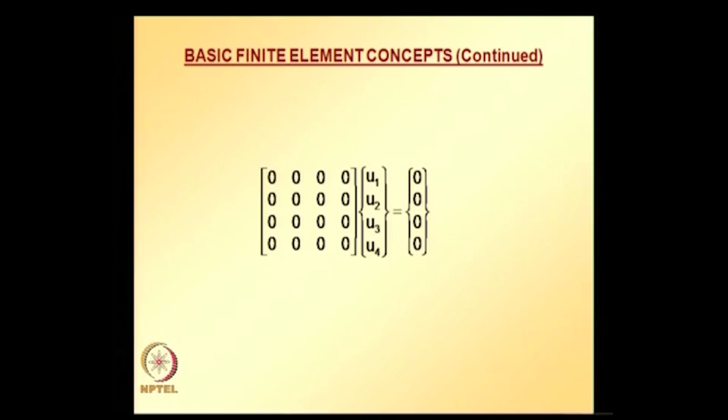What is the stiffness like matrix? It is usually a good practice in finite element method, especially when you are coding, to initialize the matrices and vectors before you start using them, because whenever you allocate some memory in the computer for some particular arrays, earlier somebody must have used it. So, some residue or leftovers will be there, and if you use it directly without initializing, it may lead to some errors.